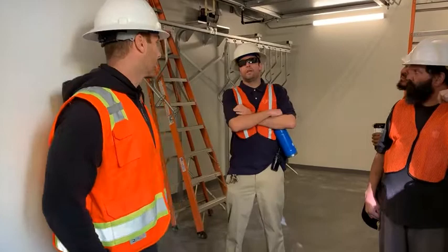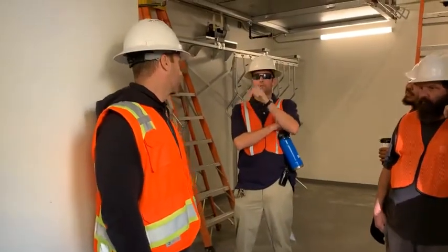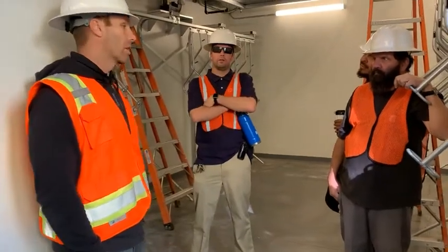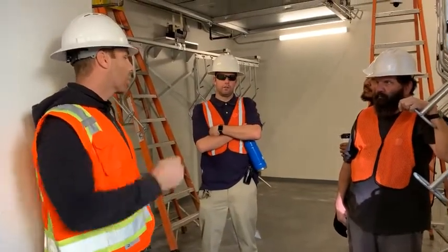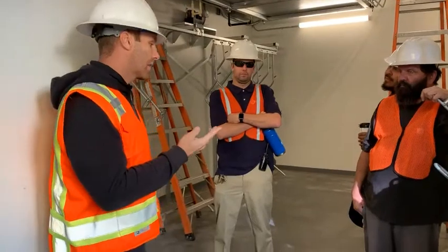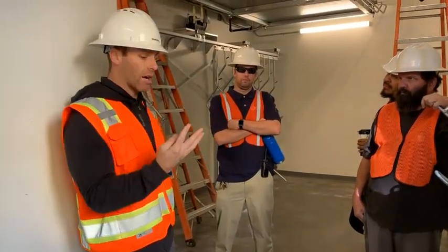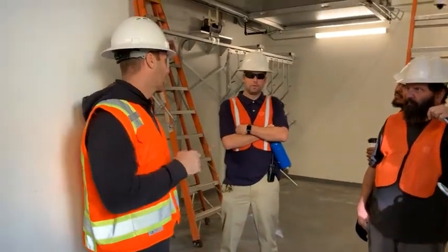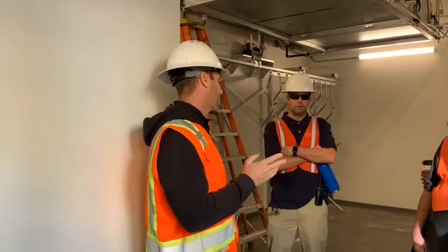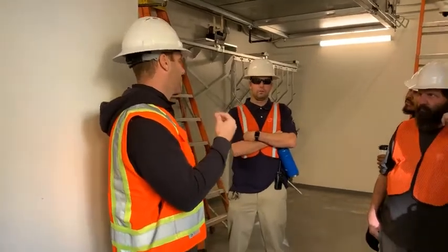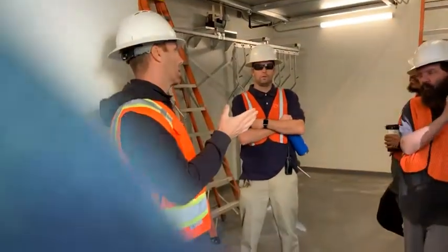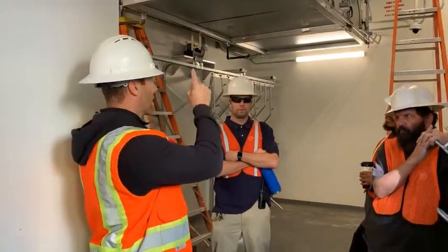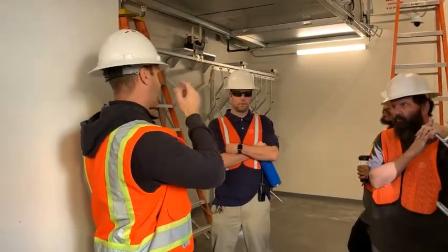So like say that switch is calling for these lights to turn on. Is it sending 10 volts of DC to turn it on? No. It's just sending a signal. There's 24 volts. So if you look at a schematic on the Cat 5, you have 4 wires going to everything. You have your communication and your power in common. So that's all it is. You have your power in common, always sending power to it. The sensor is not, it's all through intelligence. It's not physically turning on anything. So there's not a contactor, a sensor, anything like that.